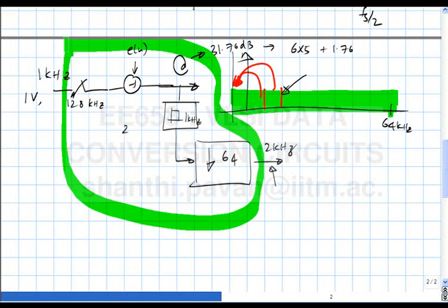no, it's not 10 bits, it increases by a factor of 64, right, so the in-band SNR will be 31.76 dB plus half a bit for every doubling of the OSR. So you are getting 2 to the power 6 times, that is 6 times half is 3, right. So plus 3 bits, which is basically, it looks like an 8-bit converter, although you have used only a 5-bit ADC. Is this clear? Okay. All right.